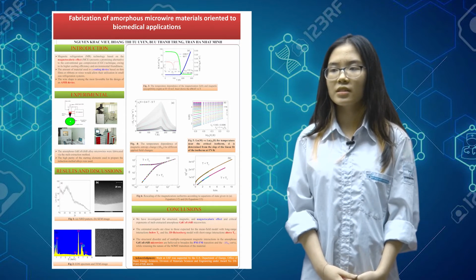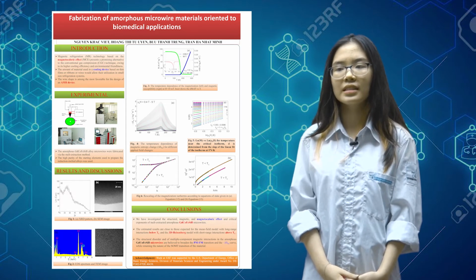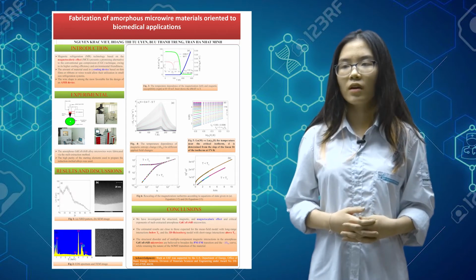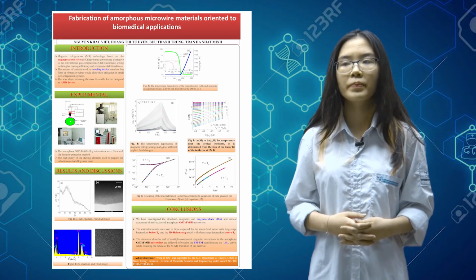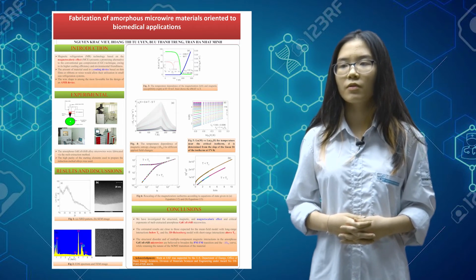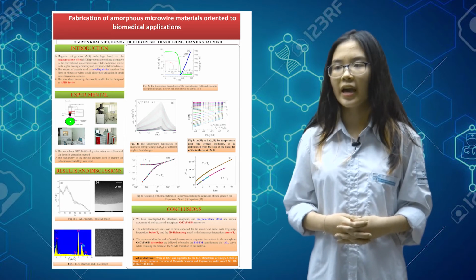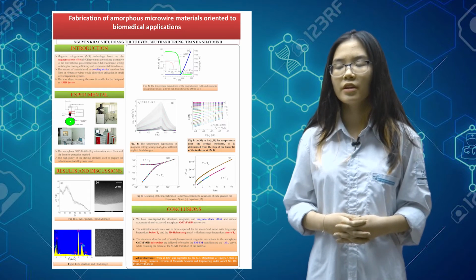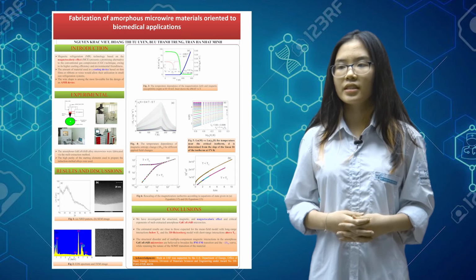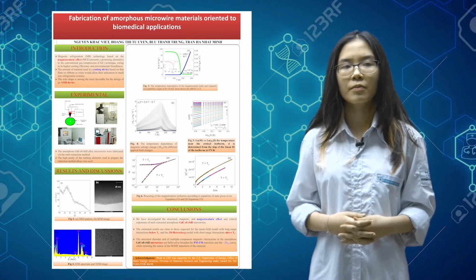The amorphous characteristic of these microwires has been confirmed by the TEM image. A typical EDS spectrum from SEM is also presented in figure 1b, confirming the presence of the raw chemical elements in the sample. As can be seen in figure 2a, the as-quenched microwire has a smooth surface. The average diameter of the microwire was determined directly to be about 45 micrometers.